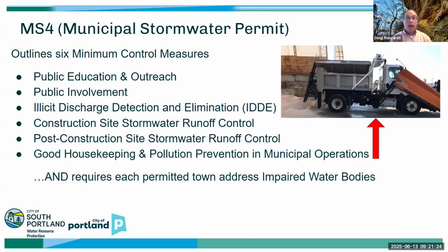If we find something at a stormwater outfall, dumping into a brook or a river or the water, we have procedures which we use to trace it back to its source and then address that source, depending on what it is. Sometimes it requires a capital project, sometimes it requires a fine. There's lots of different ways of getting at it, but it's very time consuming and can be very expensive.